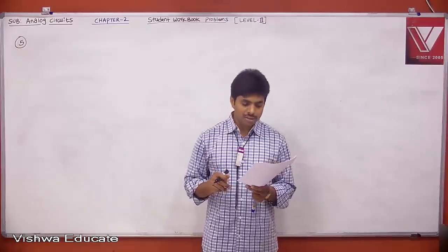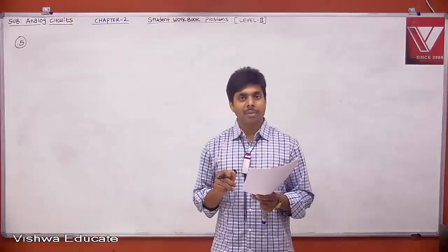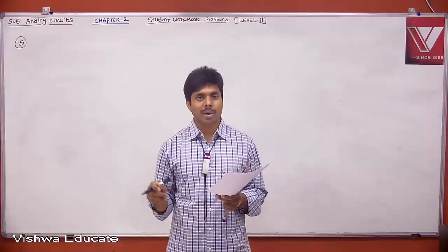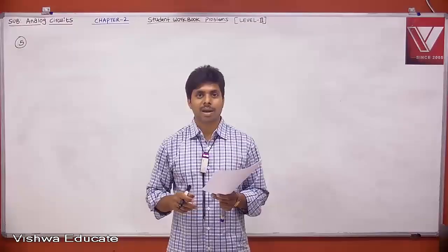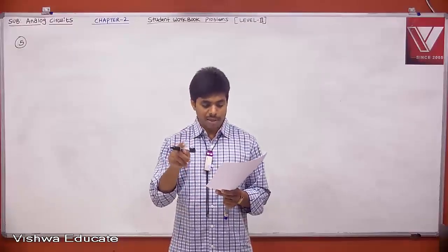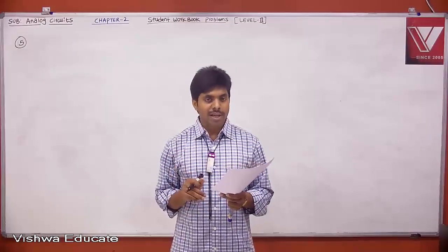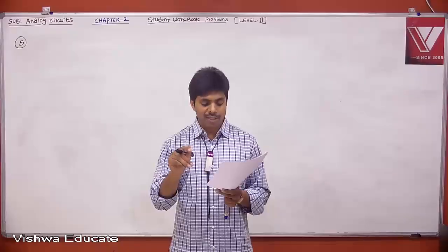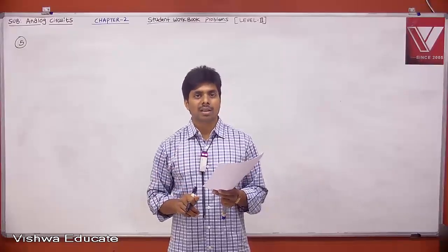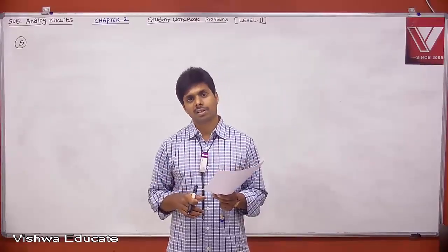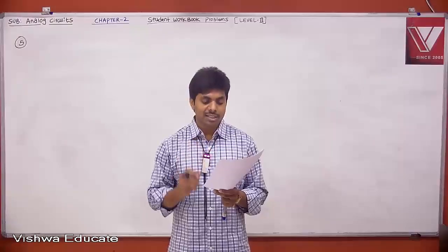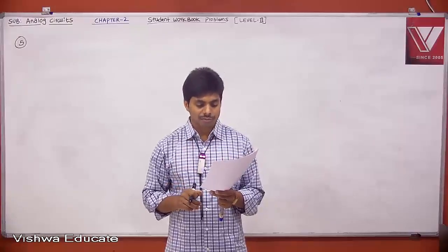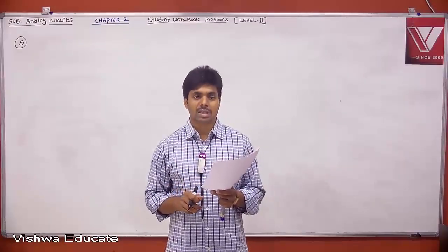But the issue with this is, if you want to bypass your feedback, RE we can bypass using a capacitor, which we had seen. That is your self bias circuit. But if you don't want to have negative feedback for AC signals, we need to have an inductor in series with RB. That is difficult because an inductor is bulky in nature. What it may be asking for is DC analysis stability. Therefore, the answer is C.